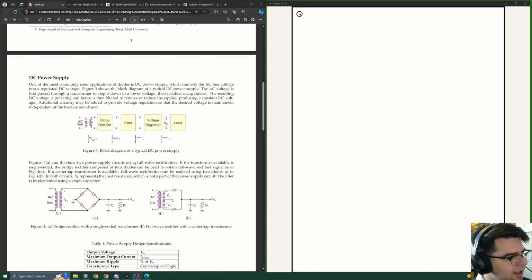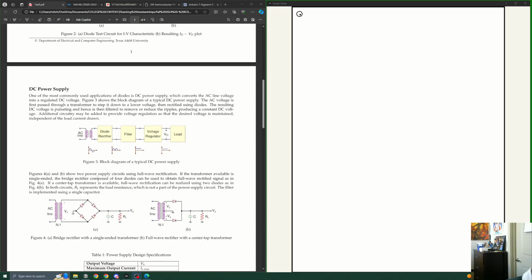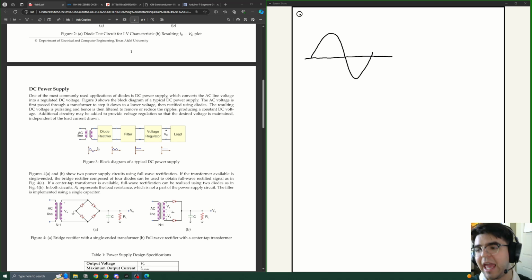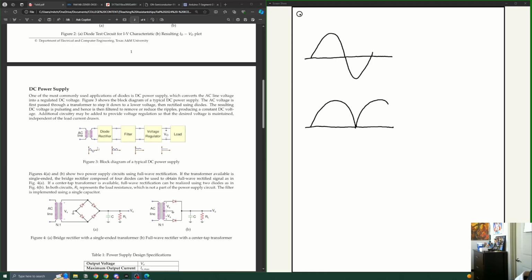And the idea is that it takes the two conduction phases, the positive and the negative, given by like this, and it tries to apply, think of it just like the absolute value of that, so it tries to then output it as two positive phases like this. And then once it's done this, we apply some sort of low pass filter, which we do with a capacitor at the output, and then this is the resistance of the load.